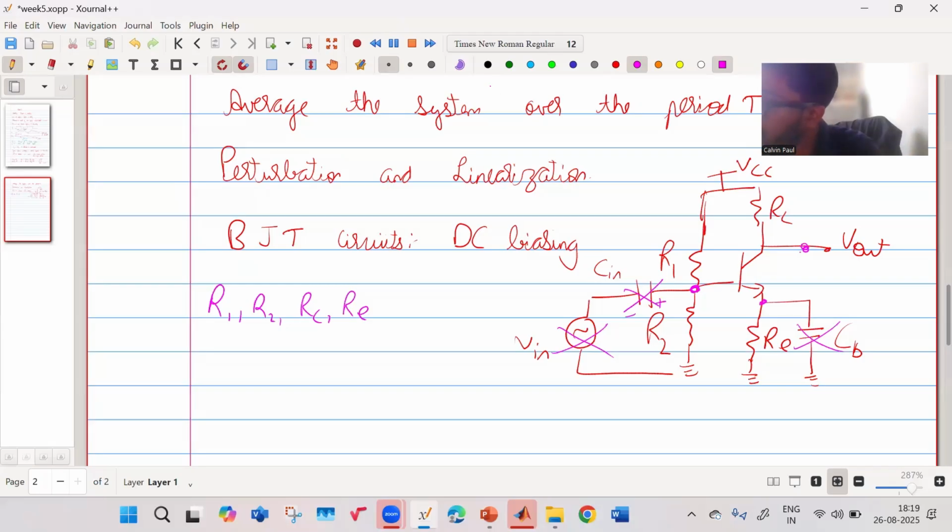This might be plus minus. This should be the way it is supposed to be connected. But if you're using a polarized capacitor and you connect it in the opposite direction, it will fail. So that's why you build a small part of the circuit, then you add more and more components. Once they do that, then they will connect these capacitors and this input to a function generator.